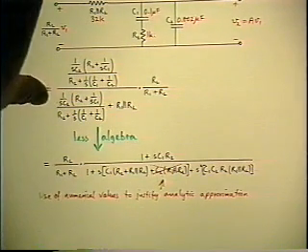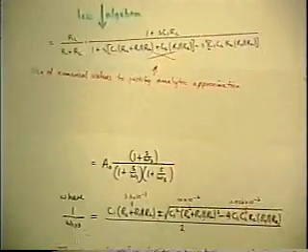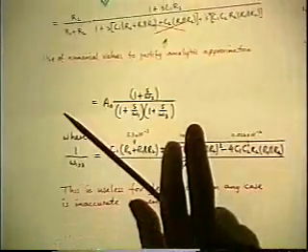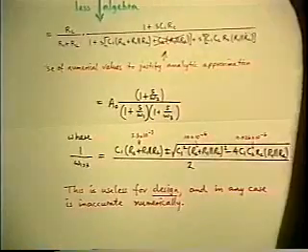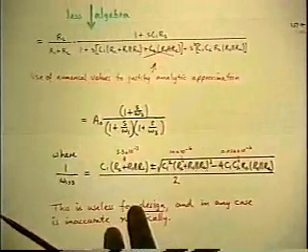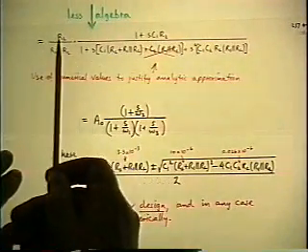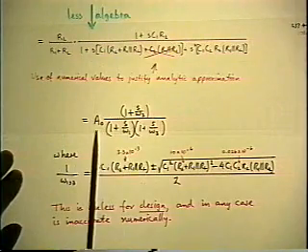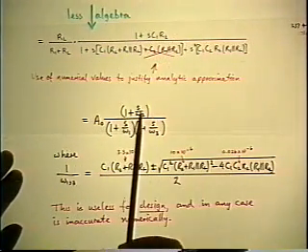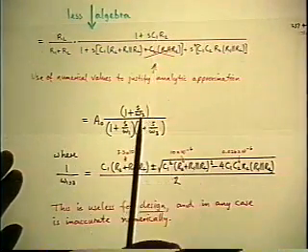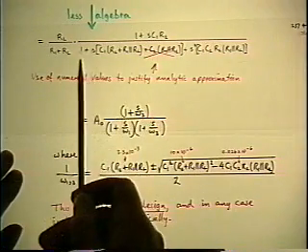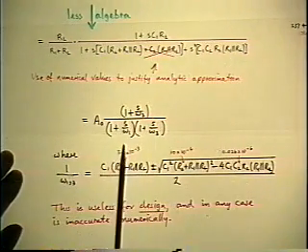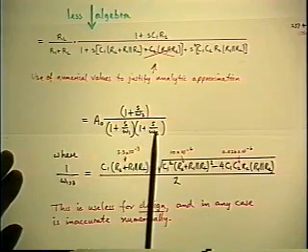Okay, the final result now, already you can see from this expression, is that we have a flat gain coefficient in front, and we have a linear function of s in the numerator that immediately defines a 0, and we have a quadratic function of s in the denominator, which means we will get two poles.